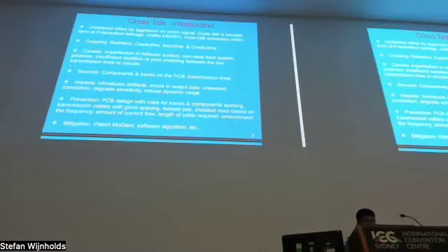By following the PCB design rules, mainly for trace and component spacing, and using transmission cables with good spacing, with either twisted pair or shielded ones based on the frequency, the amount of current flow, the length of the cable required, and the environment in that particular area. So these are the main things we can consider to prevent crosstalk.